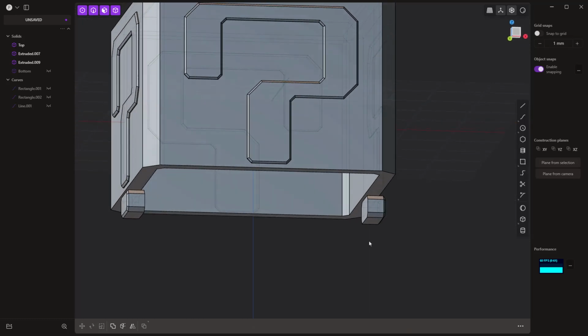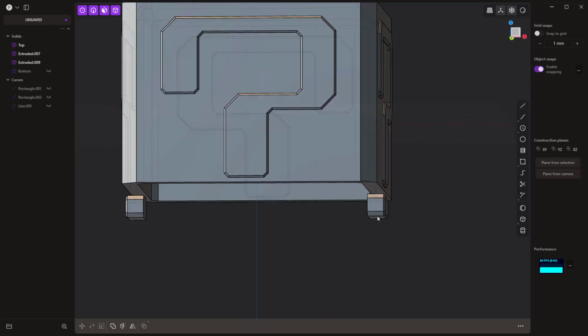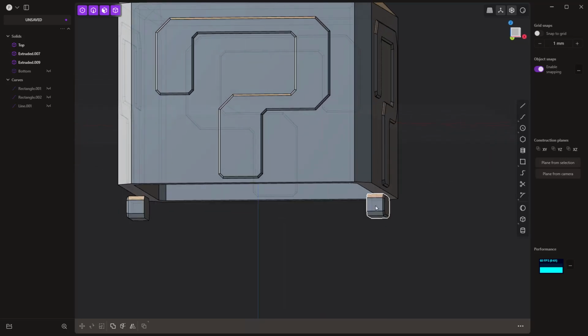There's a lot more work for us to do because we have to make a thin tab section here that's going to allow us to flex that, and then we're going to have to create geometry to remove from the bottom. Depending on how you want to approach this, you can do it one of 2 ways. You can start to remove the material from the bottom now, and then you can begin sort of customizing the offset values you need, or you can wait till the very end.